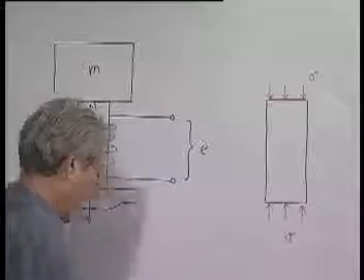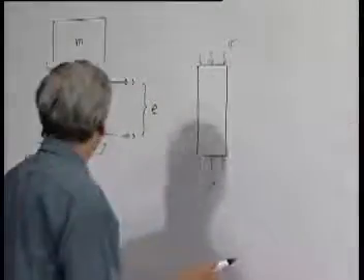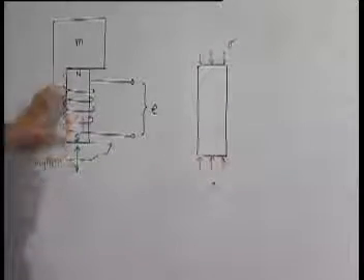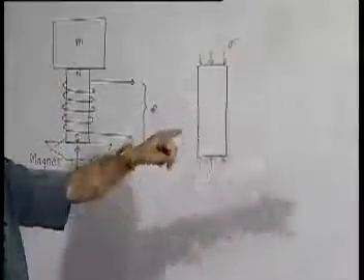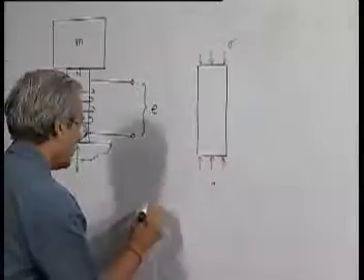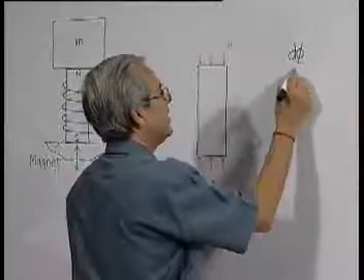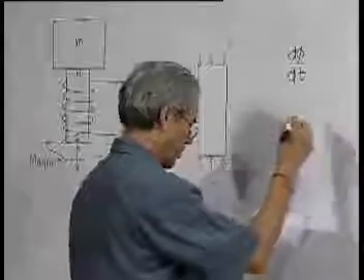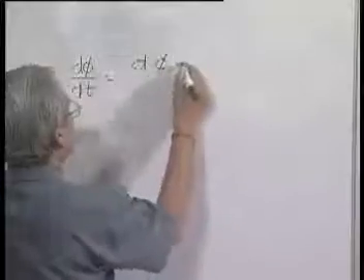So if it is a cyclic or periodic phenomenon, then the flux here will fluctuate, because this stress will produce some extra flux due to the magnetostrictive effect, as I have mentioned. Therefore, d phi/dt, which is going to generate this voltage, is equal to d phi, where phi is a function of sigma.